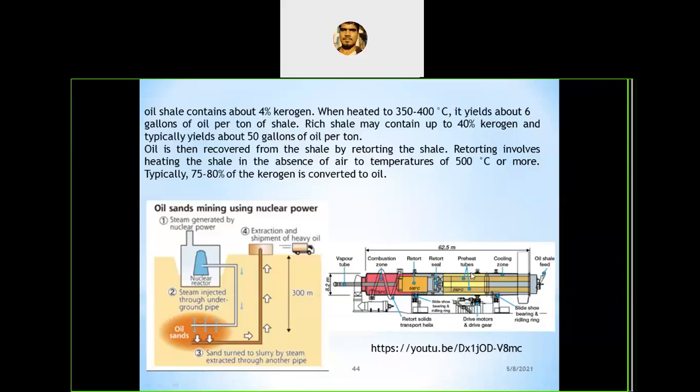The first stage of conversion is directly that oil sand from the mining is taken into the conditioning drum or a closed chamber. In that it is mixed with water, steam and caustic soda, and it forms the slurry. Then the slurry moves into the next section called the separation tank. In that separation tank, it forms two layers, a bottom layer and a top layer. The bottom layer has heavy coarse particles, and the top layer has the bitumen along with the fine particles and water molecules.